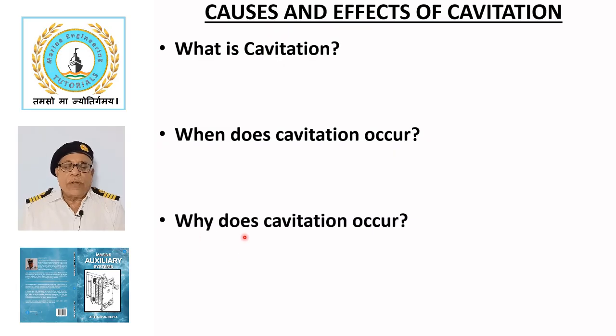Why does cavitation occur? Cavitation is likely to occur when there is restriction in the suction pipe, the liquid is volatile or its temperature is high, or the pump speed or its flow exceeds the design capacity. This problem also occurs when NPSH required by the pump just matches the NPSH available from the system.